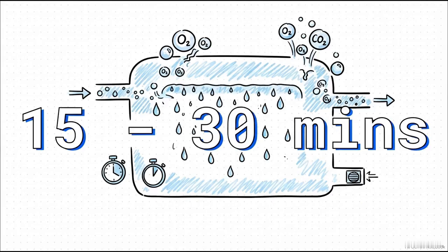It's not a rapid filter. It is a sustained, relentless scrubbing process. The water literally has to sit in this highly heated, low-pressure environment long enough to make sure virtually every single molecule of dissolved oxygen and carbon dioxide is boiled out. It's a very precise waiting game.